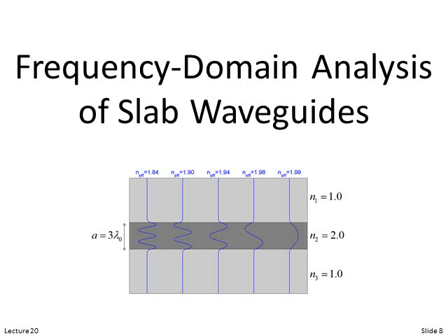into our waveguide. And we also need the same analysis to figure out on the other end how much power ends up in each of those modes. Waveguide discontinuities, whether it's bends or some kind of bump or anything like that, can scramble energy between the different modes, and we might need to distinguish how much power ends up in each of those modes and calculate how much energy goes from one mode into the other, etc.